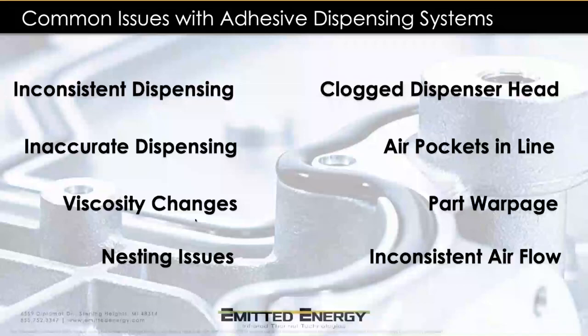And when the robot, while tuned very specifically and very accurately where to dispense that glue, if the part is not setting in the nest correctly, or if there's warp in the part, what ends up happening is that you're not dispensing that adhesive at the same location at the exact same time. So again, when we marry the two halves together for that bond, what we're then seeing is that you're not getting the correct amount of adhesive in the trap that you want to see it, and then it's causing, of course, leakage and part scrappage.